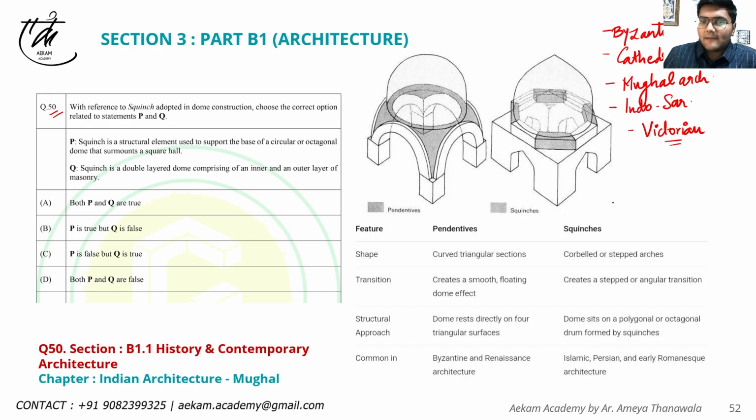Generally there are 2 broad structural elements that help transfer the load from a dome to the abutment or to the pier. The dome is circular or elliptical in nature, but it rests on, say, 4 columns on the side or a shear wall, which is square in plan.